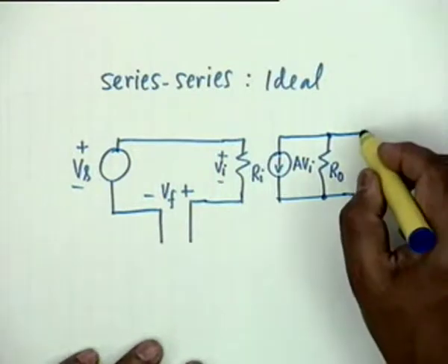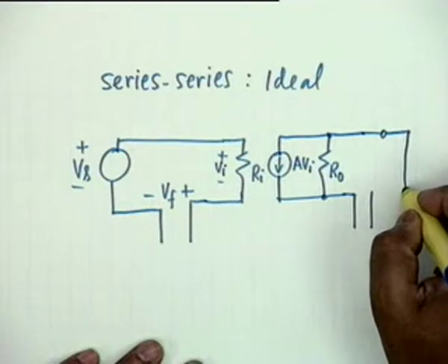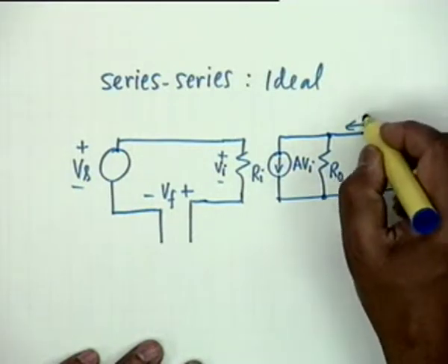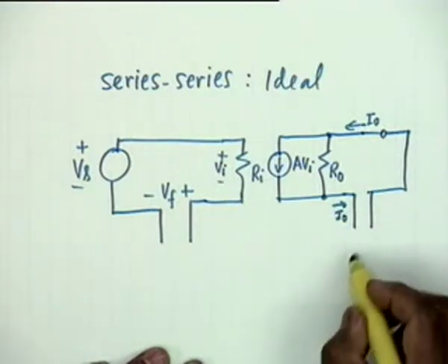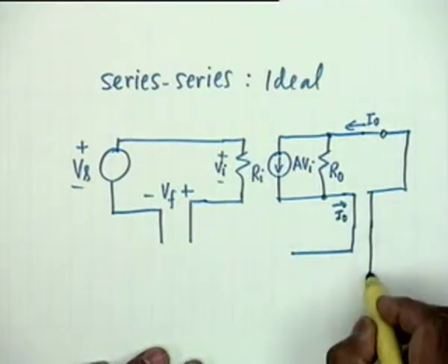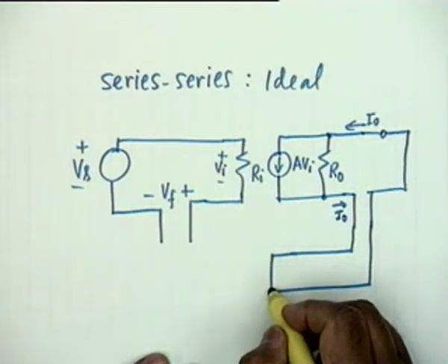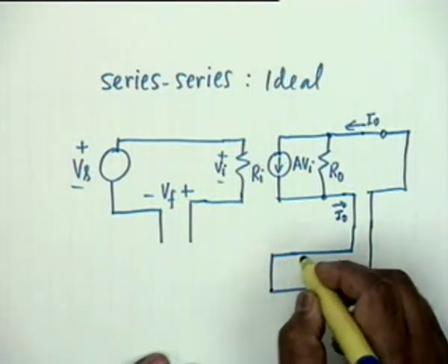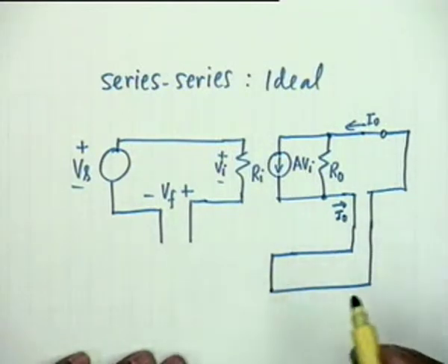This is the model of the basic amplifier, and then you have a series sampling. So, ideally this should be a short circuit. This is my I0 and this is my I0. Then what you want for the feedback network is that it should be a short circuit. So, the current here is I0 and what do you want here?